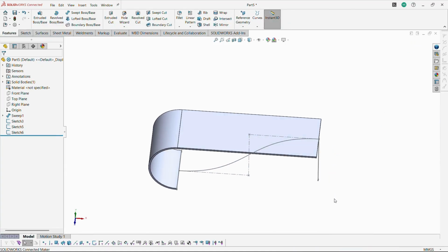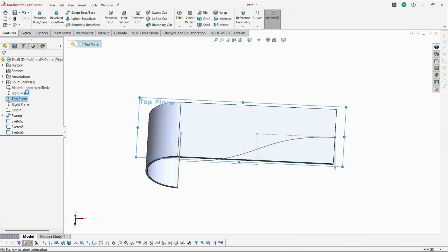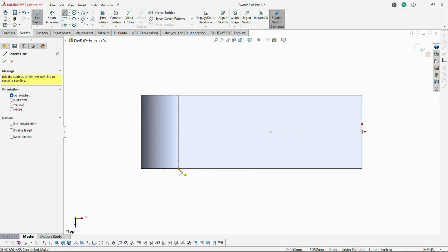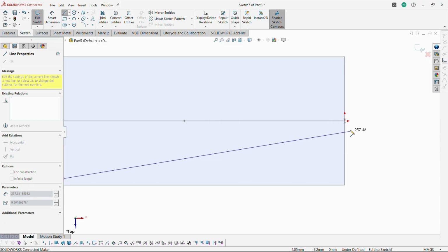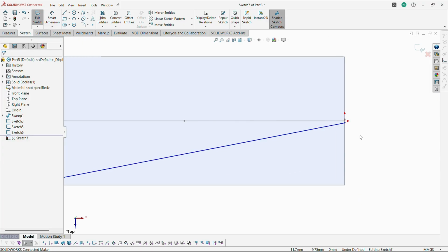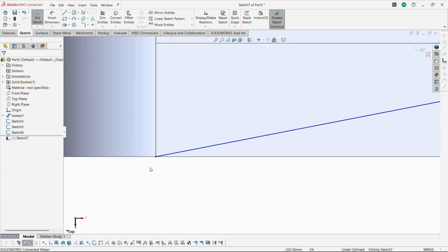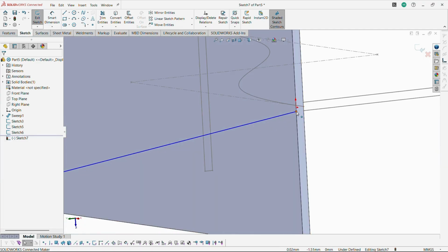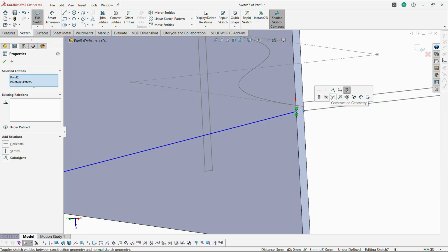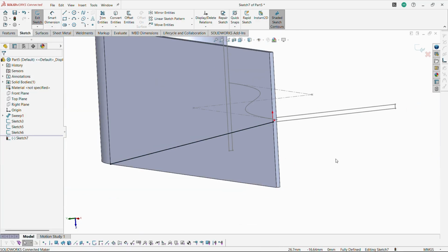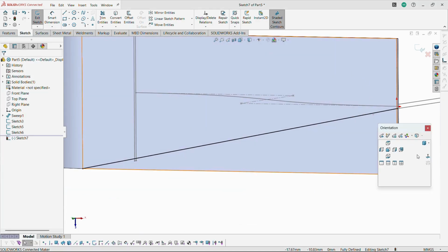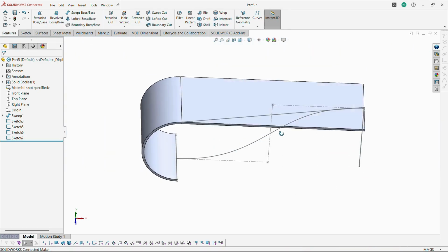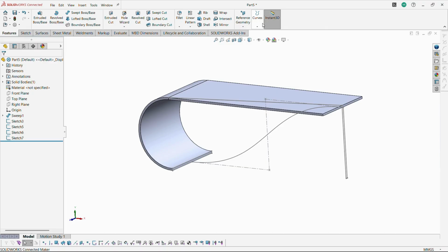The first primary sketch is drawn from the front plane. Then select the top plane and create a new sketch. Afterwards, use a line profile connecting 2 opposite endpoints, first point and second endpoint. Not on the mid positions; we switch it and position it on the corner point itself. Selecting this point again and this point again, use the coincident constraint to fix it. Look at it, it is properly fixed. Then exit the sketch right now.